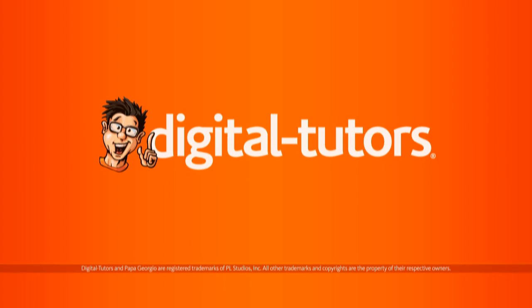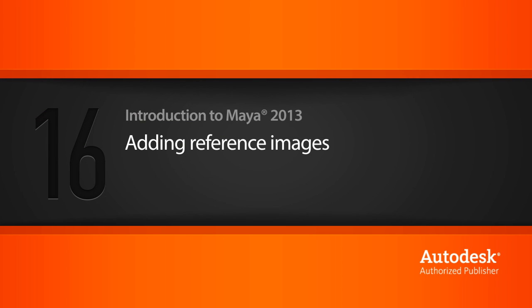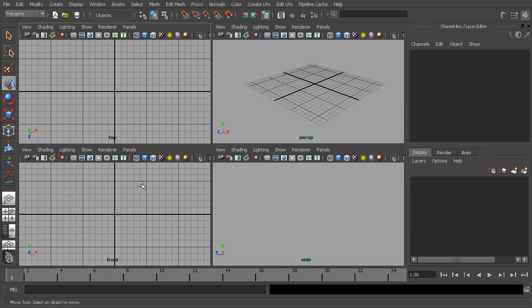Before we start actually creating any models here in Maya, let's take a look at how we can set up reference images or image planes here in Maya to use as a guide. So we have our 3D view, and if we hit the space bar, you can see that we have now our top view, our front view, and our side view. And all of these views come in handy when we're building our models because we can see them from different angles. But we can also use these views to import images to use as guides when we're modeling.